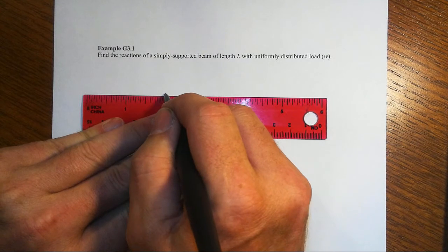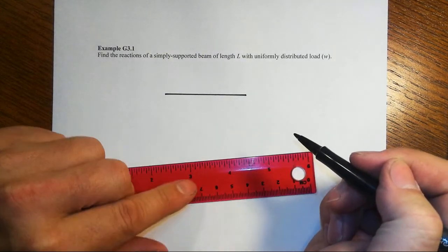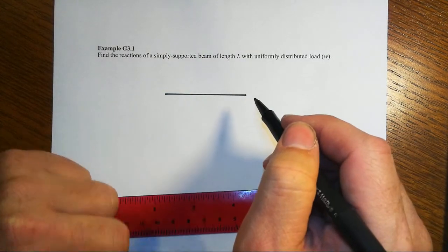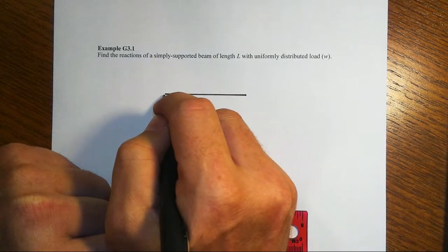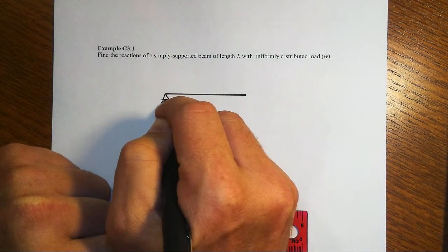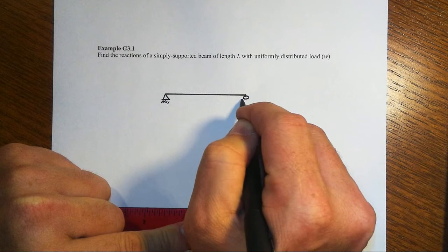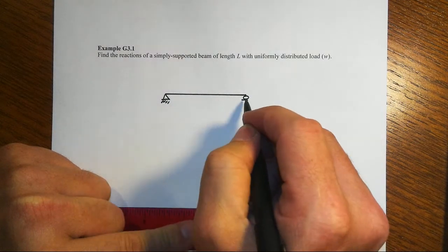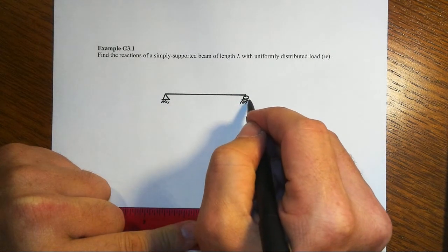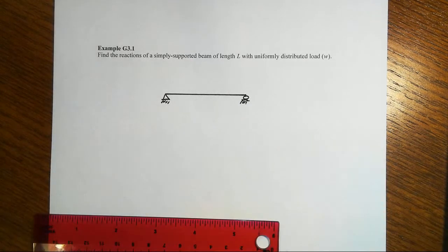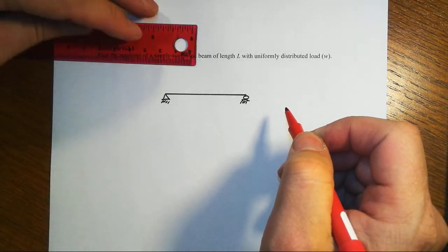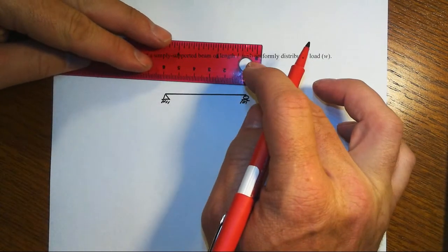Well, we have a beam. Alright, got that. What does simply supported mean? It means that we have a pin support at one end and a roller support at the other. Could be flip-flopped either side. This doesn't say that this beam has an overhang. Usually if you say simply supported beam, you usually mean you put the supports out at the end. If not, then you have to talk about what the overhang length is and if you have it on both sides.